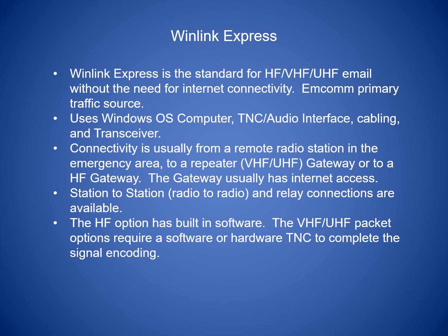WinLink Express helps fill that void by providing an internet application that is used via HF, VHF, and UHF, and it becomes an EMCOM, Emergency Communications, primary traffic source. It uses a Windows operating system computer, TNC's audio interface, some cabling, and your transceiver. And connectivity usually comes from a remote station to a repeater gateway, and that gateway is connected to the internet.